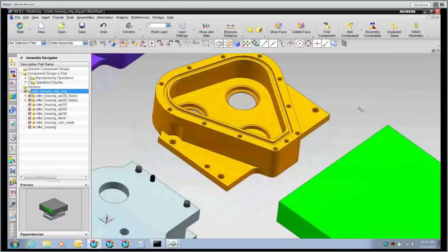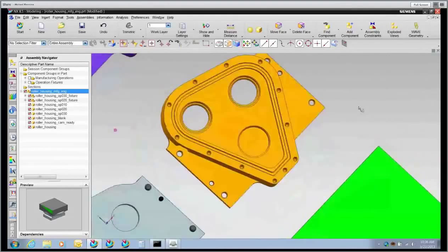And if you look at the locating holes for the fixturing, they are symmetrical. The first time we ran the job, the operator loaded one part backwards, so we ended up scrapping out a part. So we don't want to do that again. So we have to move one of the pinhole locations to make it non-symmetrical, so it can only be loaded into the fixture one way.